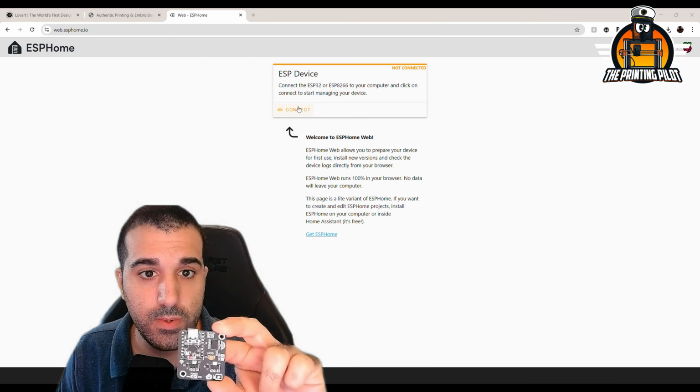And if you install everything and connect everything, and the motor spins the wrong direction, so let's say it spins counterclockwise instead of clockwise, then you come to this code here, and I also added some remarks here, and you just switch between the 3 and 4. So you put 4 here and 3 here. You're going to send the update via OTA again, and then the motor will spin the correct way. If you don't want to change it in the code, you can just desolder the motor wires and switch them.